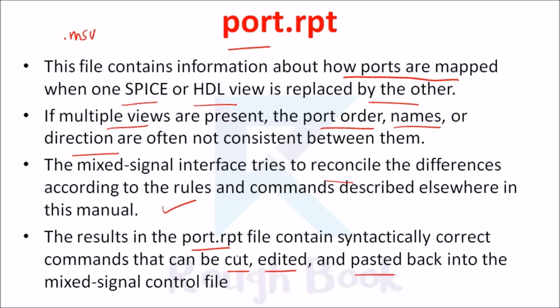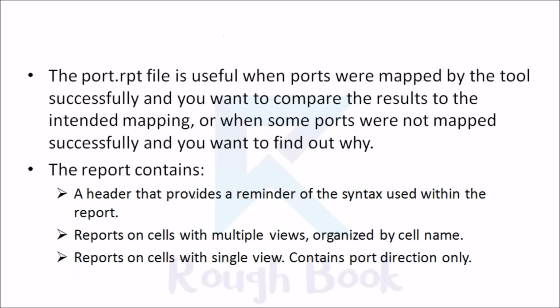So this is what it basically does. The port.rpt file is useful when the ports were mapped by the tool successfully and you want to compare the results to the intended mapping, or when some ports were not mapped successfully and you want to find out why.